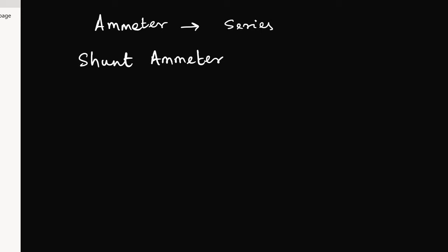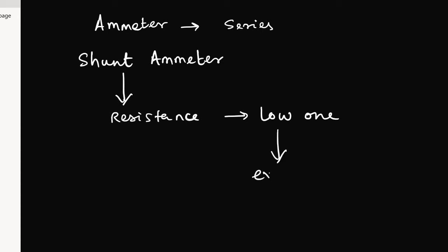Its basic function is that it is basically a resistance, same as an ammeter. It is a resistance, but it provides a very low one, so that means it will let the extra current pass through it. A shunt is used whenever we think there is a large portion of current which may harm the circuit, the ammeter, or the meter in general.